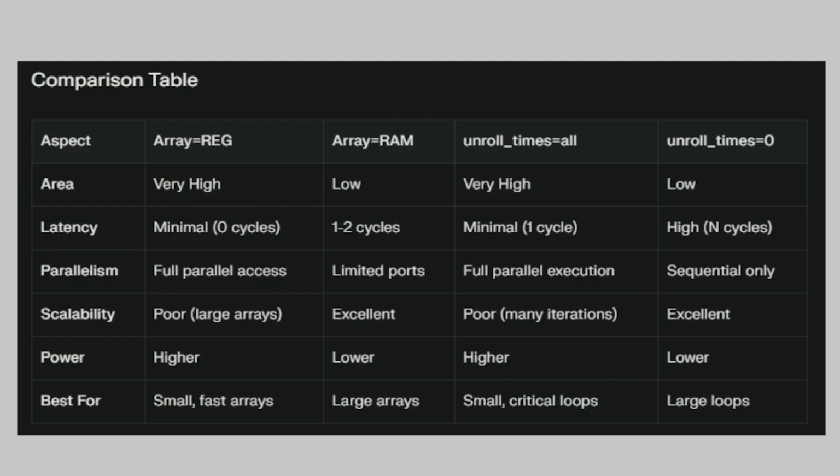But this is mainly used when the array size is really small and for requirements where data access or data write speeds are higher. If we go for RAM, this will use dedicated block memory units to store the data.